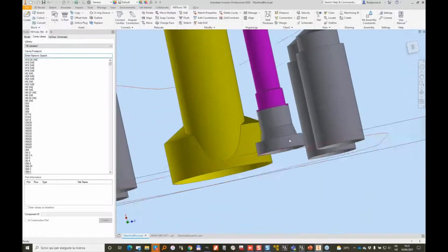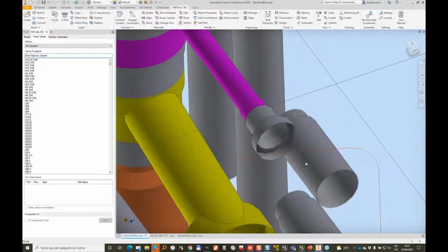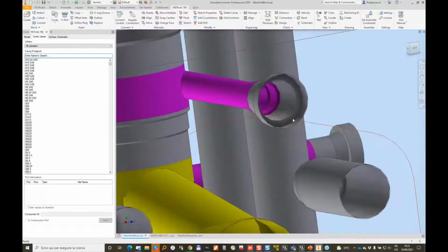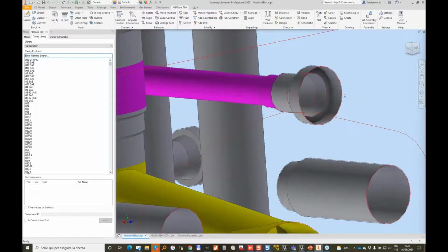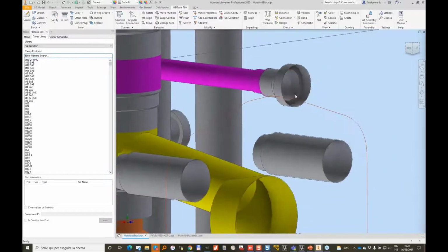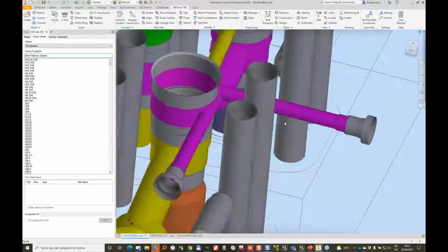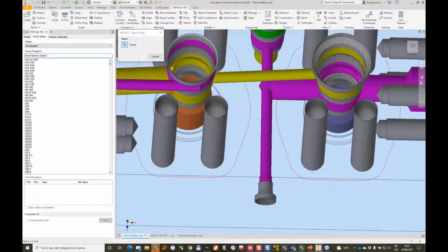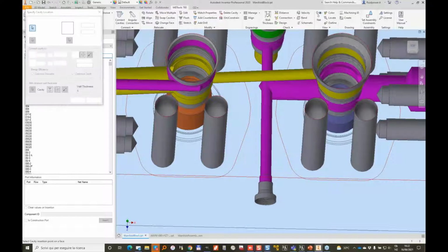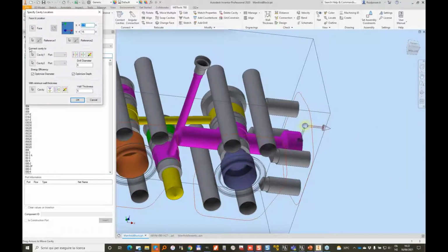And as you see now, the spot face is already synced. Although there is a small overlapping with the profile of the flange, this is not really a problem. The plug is inside the face and the O-ring is far away from the drill. Now we can copy the same drill, and let's say that we put it on the bottom face and connect the 2 drills.